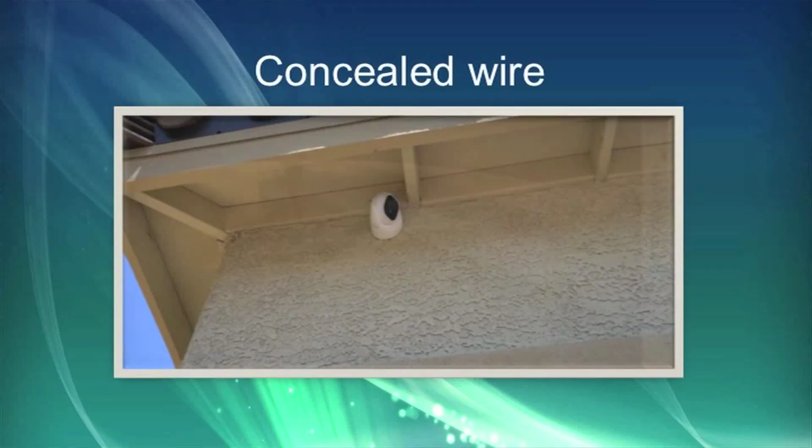Now, exposed wires are not good to look at. That is number one. Number two, exposed wires may be easily damaged by external conditions, and miscreants may also detach the cameras, disconnect them, or cut them. That possibility is also to be nullified, and too long a wire attached to the camera easily attracts the attention of burglars or miscreants. So concealed wiring is always recommended. While operating CCTV cameras, we need to look at this aspect of wiring as well.